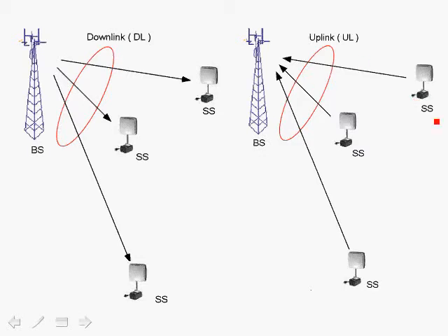As we discussed before, when the subscriber stations transmit back to the base station, they should all have been synchronized through ranging, such that all the OFDM symbols transmitted from the subscriber stations that transmit in parallel are received by the base station in a time synchronous manner, essentially coincidental. They all are received at the same time within a very small window of error, which has to be less, of course, than the guard interval. And we'll talk about that.